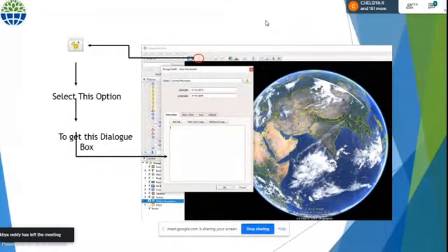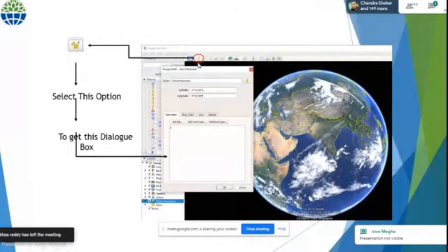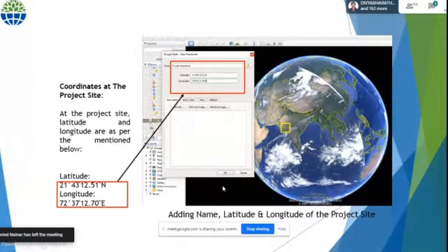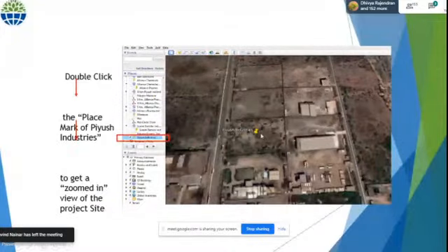So we have to put this coordinate in here. The tool is provided already. If you click on that, this type of bar will open. Immediately you have to put it in by typing, otherwise you can copy and paste. After putting it in, click on OK. If you click OK, then you will see this type of screen.